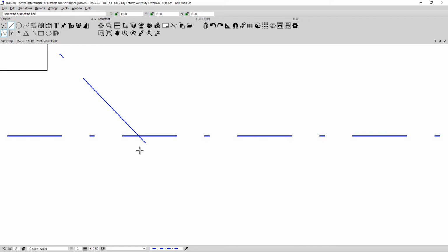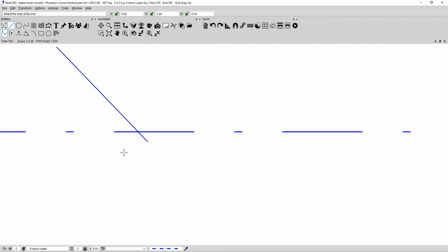So this one would be a good position for me to show you how to trim a piece off the line. Hold your cursor over the line towards the end that you wish to trim, past its halfway mark. Wait for a diamond. This time press the right-hand mouse button and a new menu will appear with some options. Choose the word trim, and you now have the ability to make the line longer or shorter, or select a line specifically that you wish it to trim to, and that line is neatly trimmed to this one.